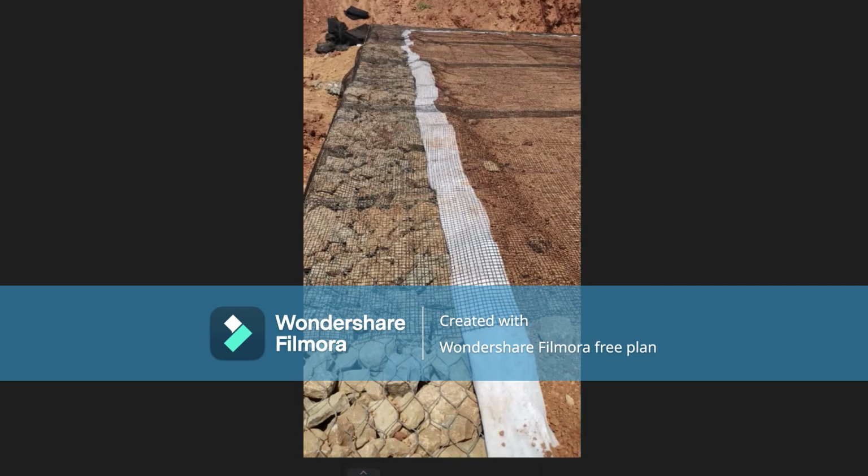After providing the gabion boxes, stacking each on another in every layer, after one layer they attach the geosynthetic, the geogrid, with the gabion box, and each layer has a different tensile strength, with the geogrid provided at different levels. The geogrid is attached with the gabion box for stability of the wall, so it does not slide any more.